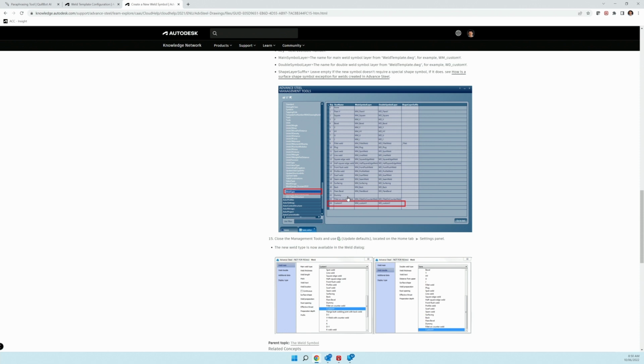So an application for that is if you have a weld for holding an assembly together, but you don't want to actually call up a weld, you just wanted to make the 2 beams join together for the purposes of being able to create an assembly drawing. You could use a dummy weld. We've actually created our own weld type called an assembly weld, which does that same functionality.